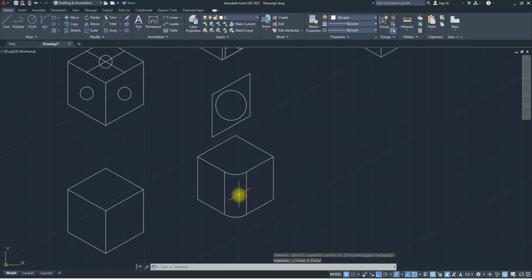If you are in this position, let's do reverse engineering. You are in this position, how can you go back to that sharp corner? You can't. Yes, you can just use your extend command. But then, if I do this, extend this, wherever they meet the line, I extend this one out. You can see that in this case, I can't extend. So the reason why this extend was going is because there's a line here.